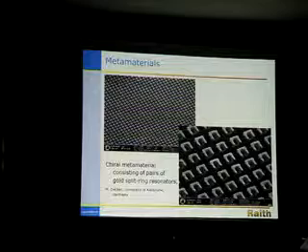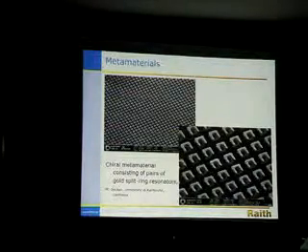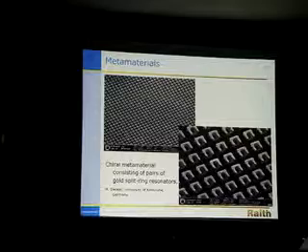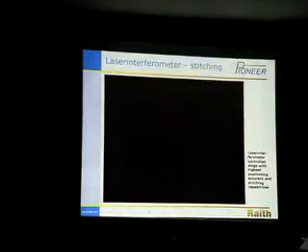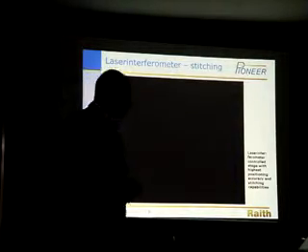And especially for optical metamaterials, it's really important to control material dimensions down to the scale of 10 nanometers and below. Otherwise, the optical performance will change drastically, and you'll see a few examples of that. So again, this is a 100 nanometer scale bar, so these are sub 100 nanometer structures that are being carefully overlaid above one another for these metamaterial tasks. So the Pioneer system, like all vector scanning lithography systems, is capable of stitching.